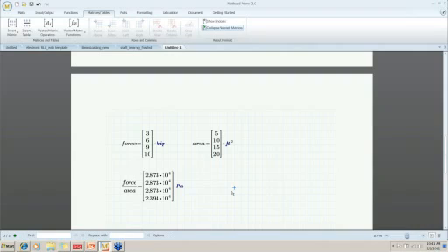But you'll notice the units are a different font, which is nice. We already covered that. If we wanted to change this unit to a different unit, if we don't want that in pascals, we could change it to KSI, and now it's in units of KSI. We could change this to inches squared if we want. If we change the definition here, this result is going to be updated because now these numbers are going to be in square inches instead of square feet. So there's that math operation. This is using Mathcad matrices. Let me just write that down.